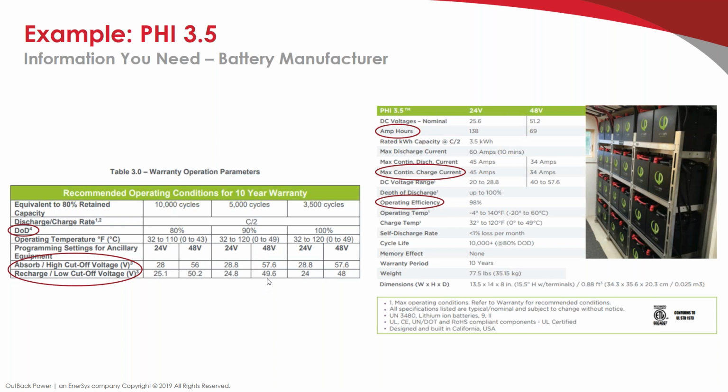Okay, I think I answered this one. How do you set for 80% state of charge or depth of discharge? With the Skybox, it's easy enough to do. If I understand your question correctly, if you want 80% state of charge to be your maximum, then you would just set your state of charge maximum to 80 and not 100. But if you're looking for 80% depth of discharge, so we're going to drain our water glass to 20% because we've drained it by 80%, you would set your maximum to 100 and your minimum to 20.